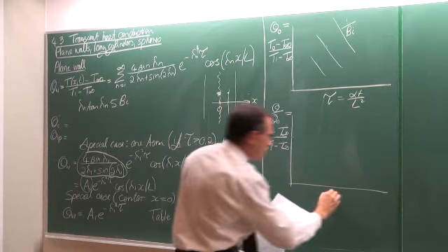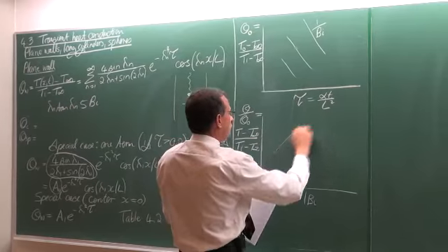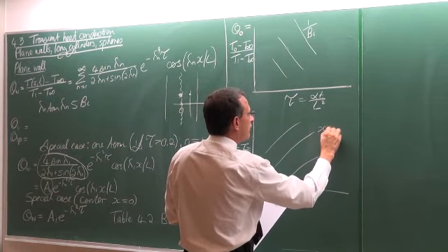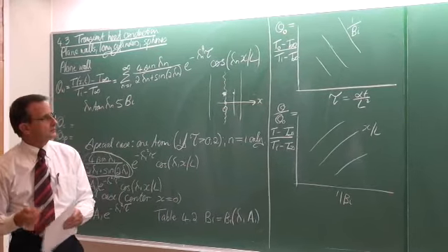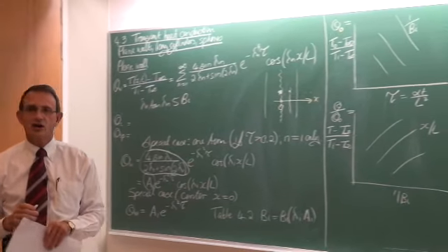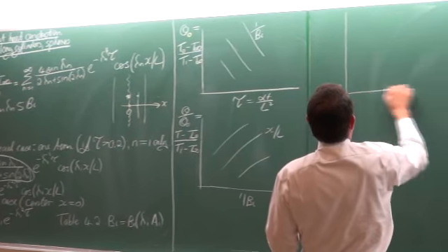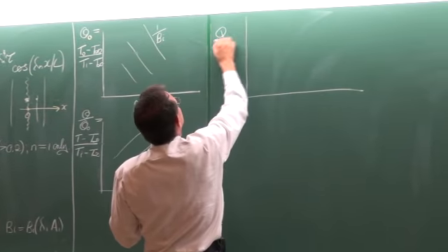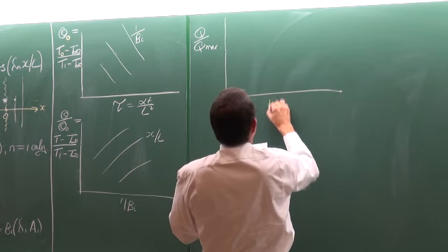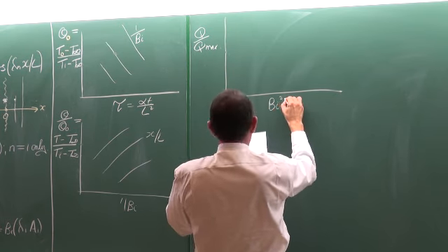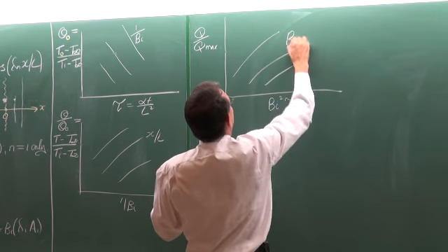And this is now given as a function of 1 divided by the Biot number for different lines of x divided by L. Okay, so that is the second Heisler chart. And the third one gives us the heat transfer. So Q divided by Q max, and that is given for the Biot number squared multiplied by tau for different values of the Biot number.